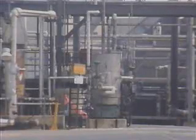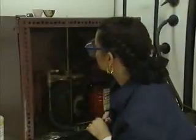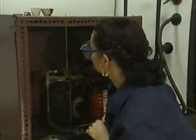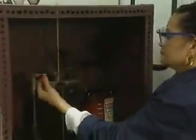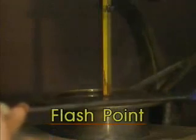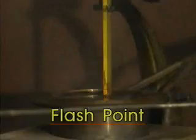A high pour point indicates that the lubricant needs higher temperatures to flow. The pour point is especially critical in machinery that must run in cold weather and in equipment that's used in refrigeration systems. Two other temperature-related properties of lubricants are flash point and fire point. The flash point of a lubricant is the lowest temperature at which the lubricant's vapor will ignite when it's exposed to a source of ignition.